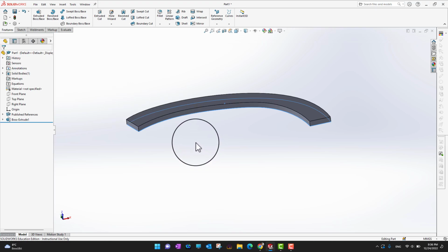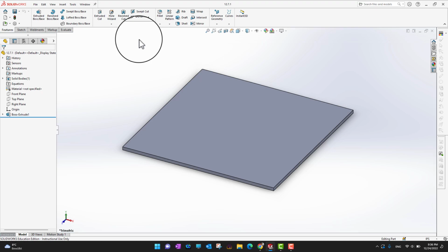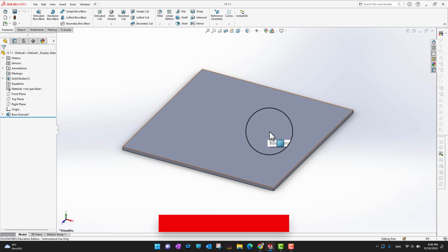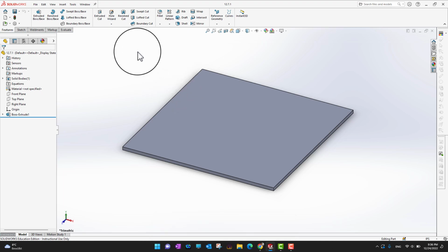These are my first two connectors, and now there is another part on which this part is going to stick. Let's go and see the other window. Right now I have this part, and I want to stick that part into it, and then I want to create multiple magnetic mates. As this is a part right now, I want to bring it to the assembly, and then I want to create a ground plane on this part as well.